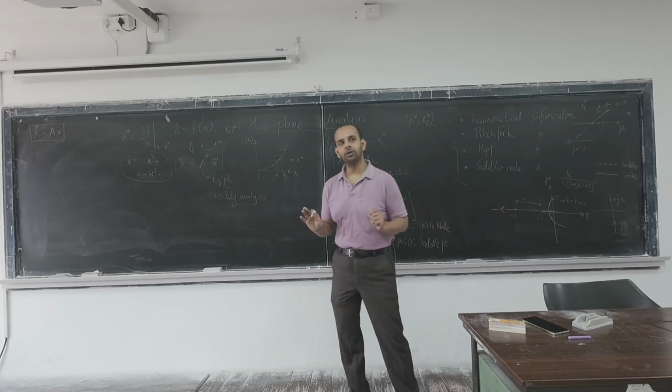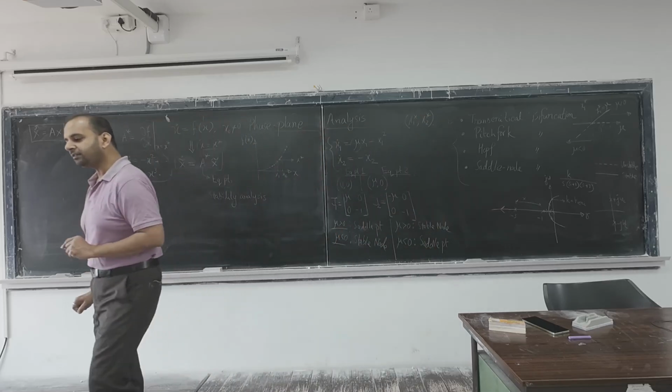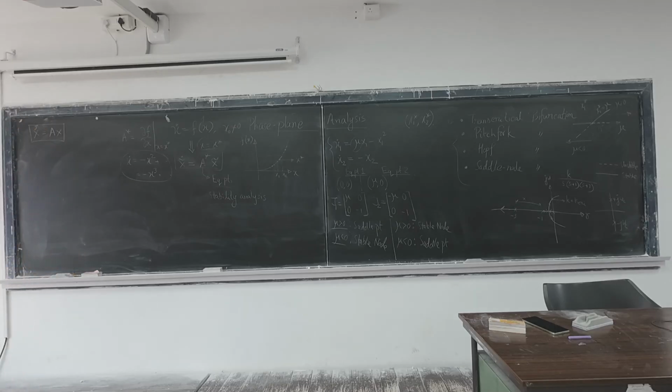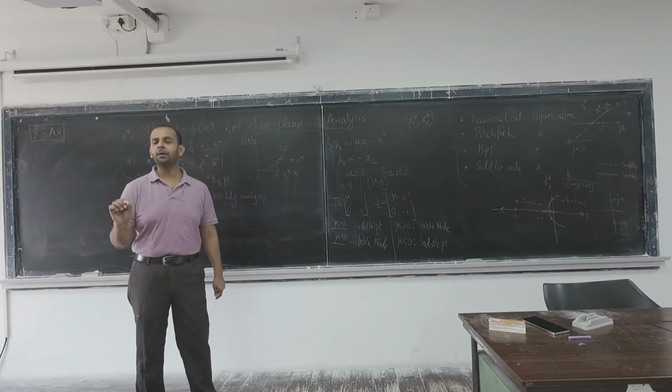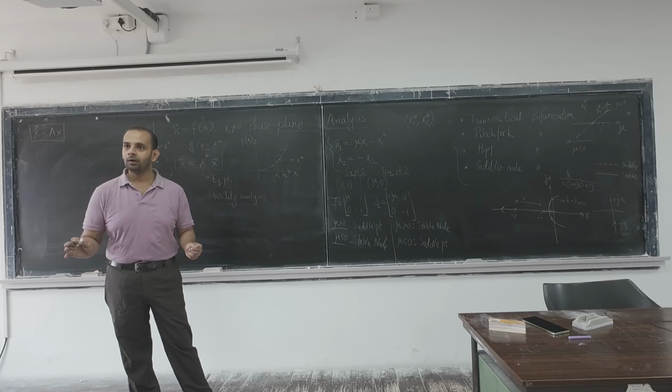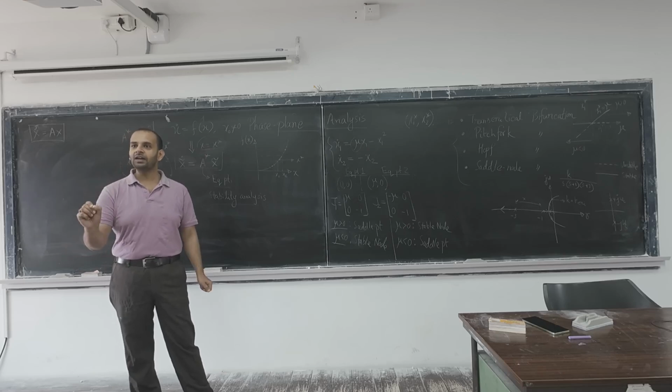Please be very careful about that. Once again, for a linear system, we always say it is stable or unstable, I mean either asymptotically stable, unstable or marginally stable. We never worried about the zone of the initial condition or anything else, right? But please be careful, for nonlinear systems we cannot comment about the stability as a whole. Even if it is unstable, that is also local in nature.